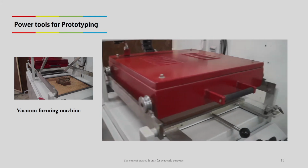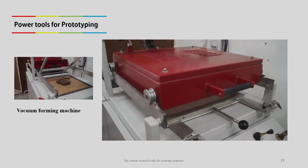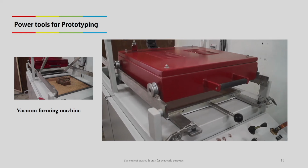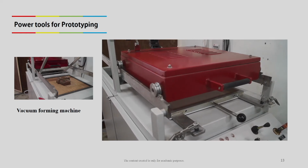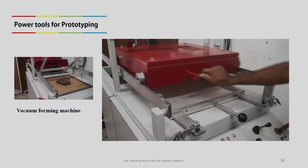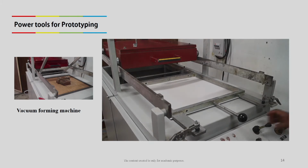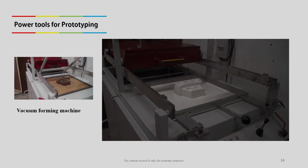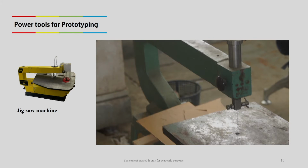The red part is heating part where hot air is blown. After some time we have to check whether it is soft or not. Now, the mold is up and vacuum has been created, and the plastic has taken the shape of the mold. Next stationary tool is jigsaw machine.